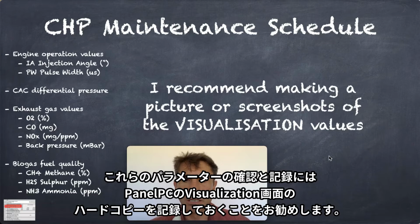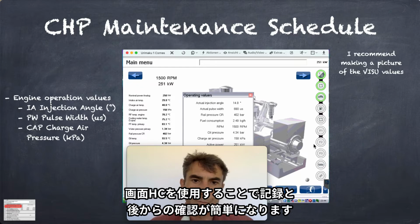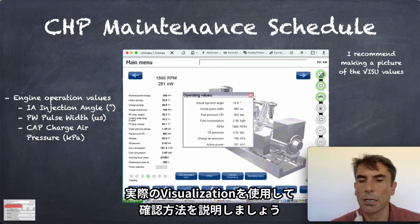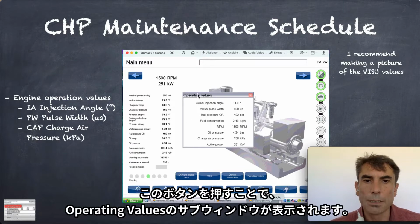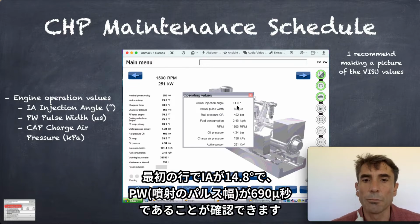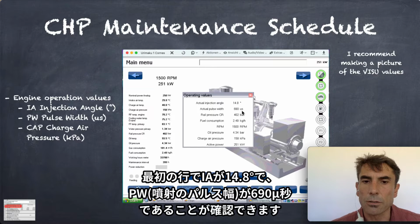I recommend always taking screenshots or a picture of the different menus in the visualization, so it's easier to record and easy to use later on. For example, if we log into the visualization program with our login password, then we can open the operating values with that button here. We open that window, and we see the important values like the injection angle. For example, here it's 14.8 degrees, and the active pulse width, for example here, it's 690 microseconds. It's a very important value and gives me some figures on how the system operates.